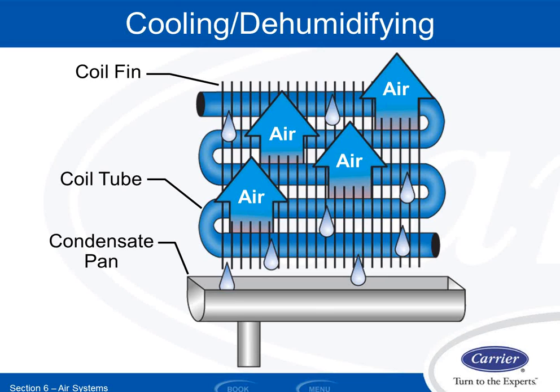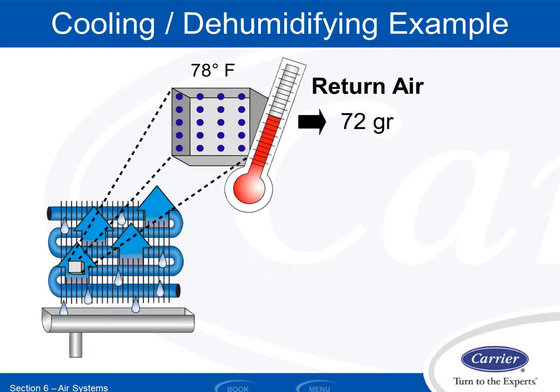I'm at the dew point. If I get one more drop of humid air coming in, it's going to condense and drip off onto the coil, run its way down the coil into the drain pan, and then drain away. So I need surface area to do that, and I need fairly slow air motion to do that.